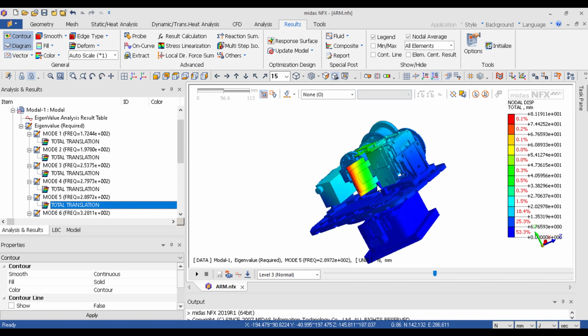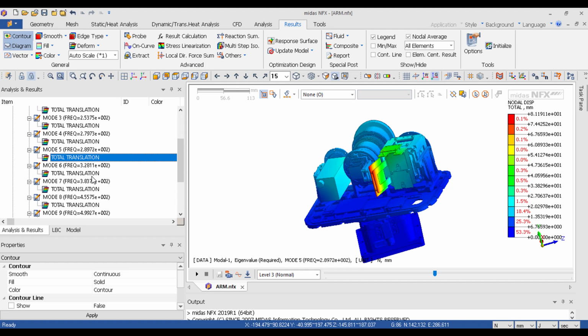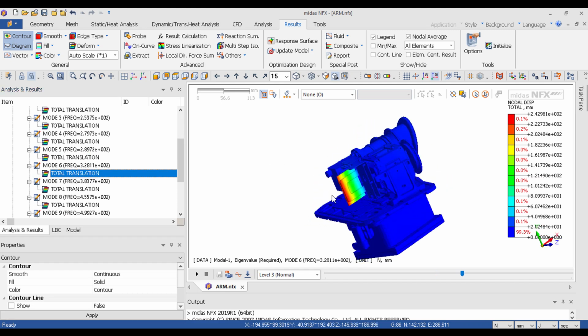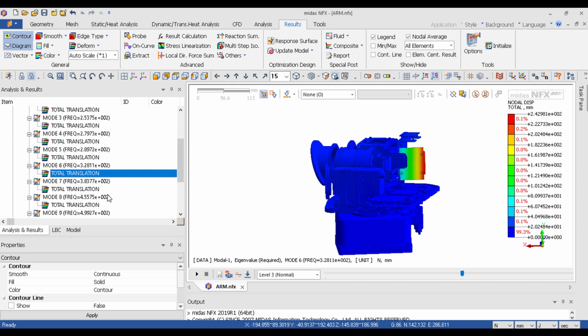We see here that the digital PCB has the biggest deflection. This is the excitation here in the 5th mode. The 6th mode also excites this board and the mounting bracket which holds it. Those are the 6 sensitive frequency modes, where the system has a resonance at these frequencies.